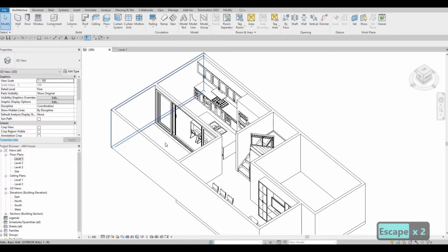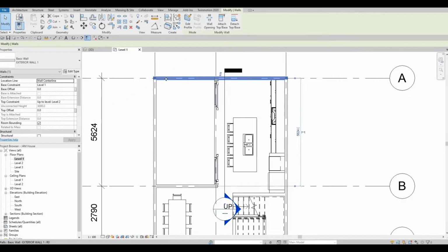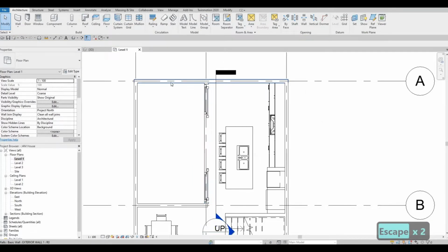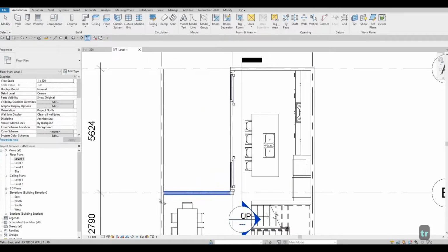At the same time, we're gonna put grass around there. So first I want to pull back this basic wall, exterior wall number 1, because I want the border wall to be smaller, and I want it to have a different material. So I'm going to type in TR, that's trim and extend, and then trim and extend right here.